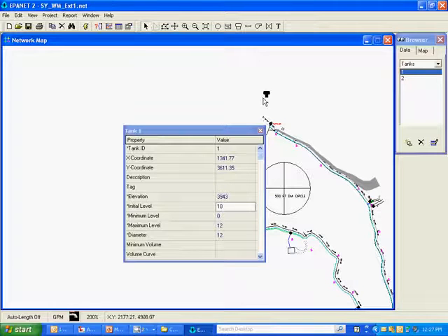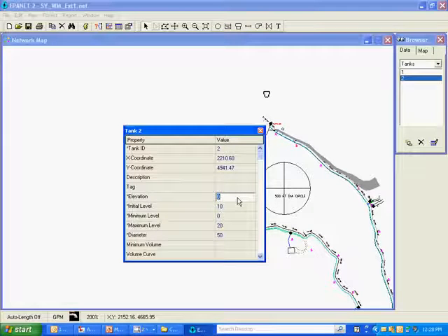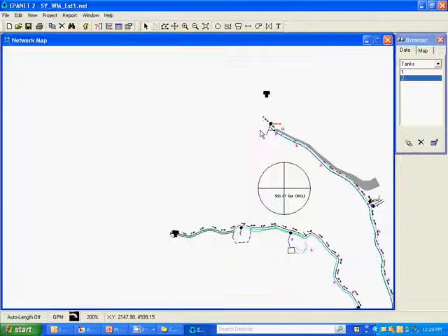And let's go ahead and set the elevation for the existing tank, which is 3757. And let's make this a large tank. Let's make it 100 feet. And let's do a maximum level of 100 as well. We just don't want this tank to run out of water during the modeling. Actually, make that 1,000, because we just want it to be a supply of water. We're not interested in actually modeling or changing it during this design process. I'm going to pause right now and continue in the next section.